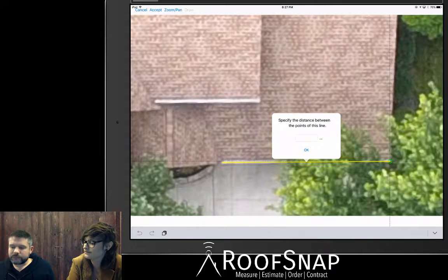Okay. The ridge may also be an option. And don't measure a 5-foot ridge when the building is 40 square. Measure a long ridge or a long eave. That's going to give you the largest spectrum for setting scale for the entire roof. Gotcha. The longer the measurement, the better.